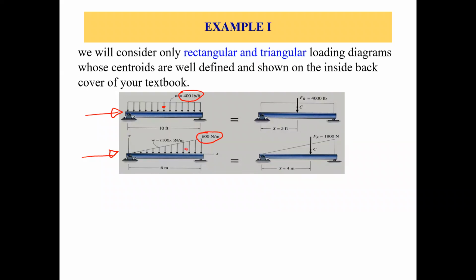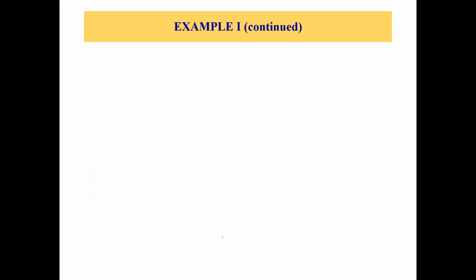So along the x-axis, it will be 2/3 of the length from the base, from this point, and 1/3 from this point, right? So that gives you the location of the centroid along the x-axis, along the length. Okay. All right.